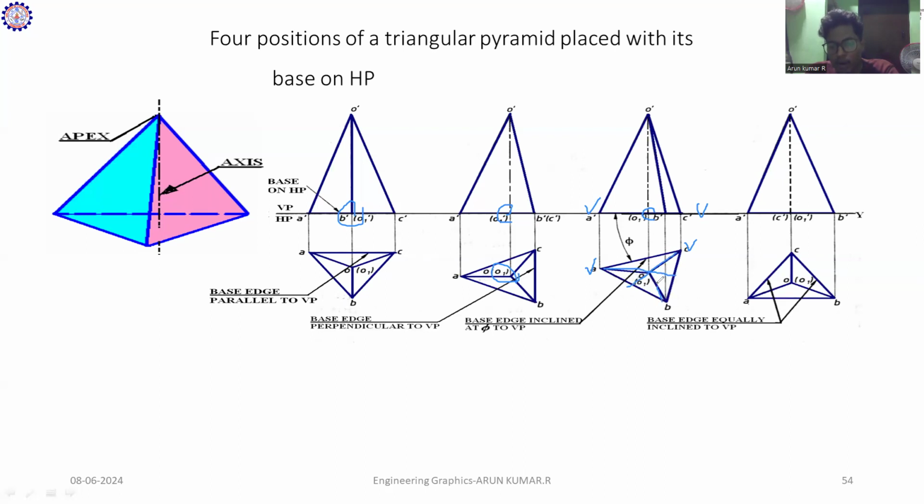Okay, so if you join all the lines, you get the center point of the given solid. Once you have constructed the center point, you proceed downwards with the lines, like above the XY line. The prism has a height value mentioned in your problem. Let's consider the height value is 25. So that 25 value you construct towards the XY line. Once you construct the 25 mm length, that point is called O dash.